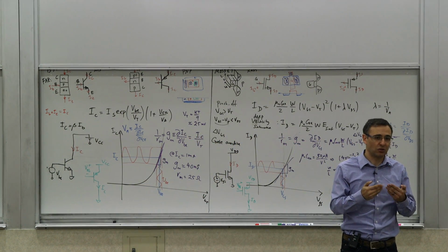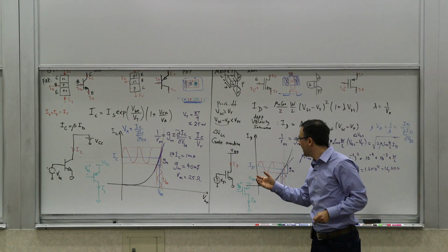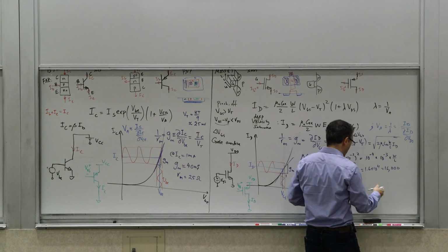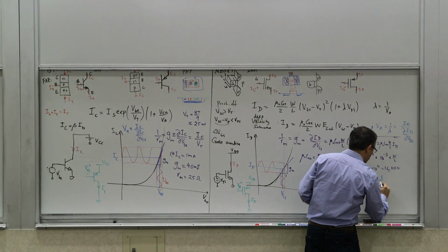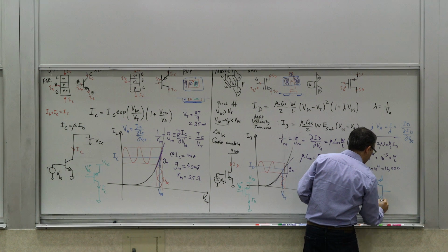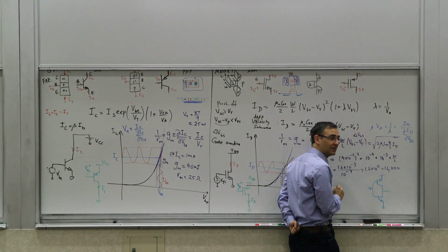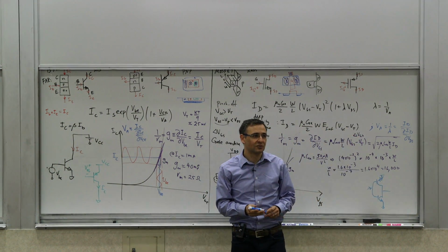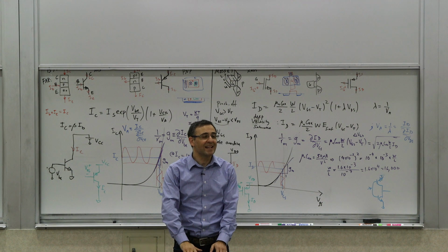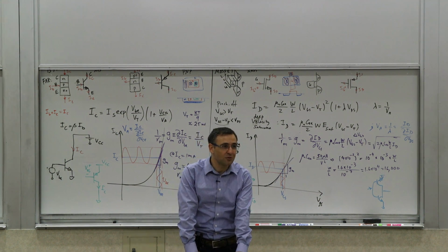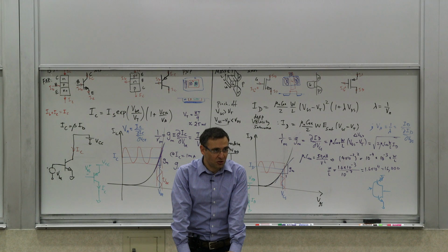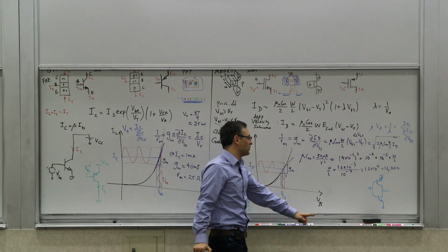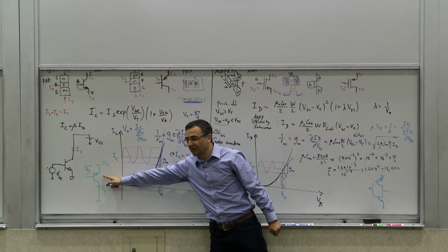So that's why instead of that, you come and create, with these guys, the MOS gate, which we haven't talked about, but you're probably familiar with. You can have an NMOS and a PMOS, and at least in the basic model, you're drawing no current here, and when the gate is not switching, there's no current here. So there's no static current. And most of the transistors that are used in digital circuitry happen to be of this kind, not that kind.